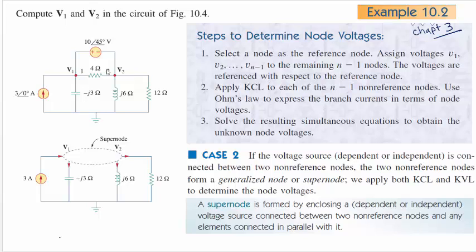So here's the circuit, and this time they didn't give you the frequency it's running at. They said there is some frequency and some capacitance, and when you compute the reactance, XC will be minus J3 ohms. Similarly for this inductor, its reactance will be J6 ohms. Then you have this voltage source that has a phase angle of 45 degrees with respect to the phase of this current source. But both are running at the same frequency. We don't actually know what the frequency is, but they're both running at the same frequency.